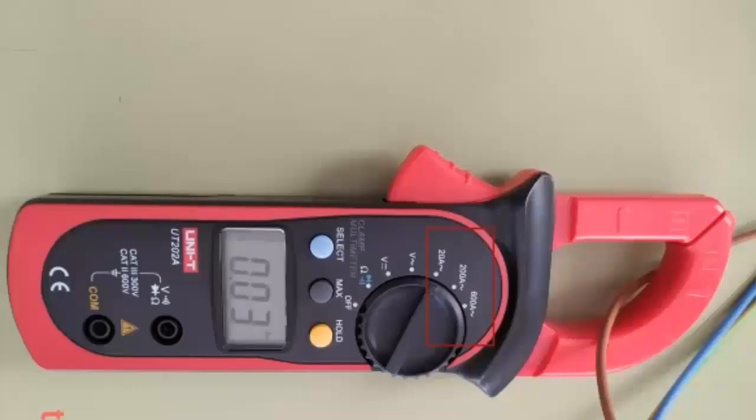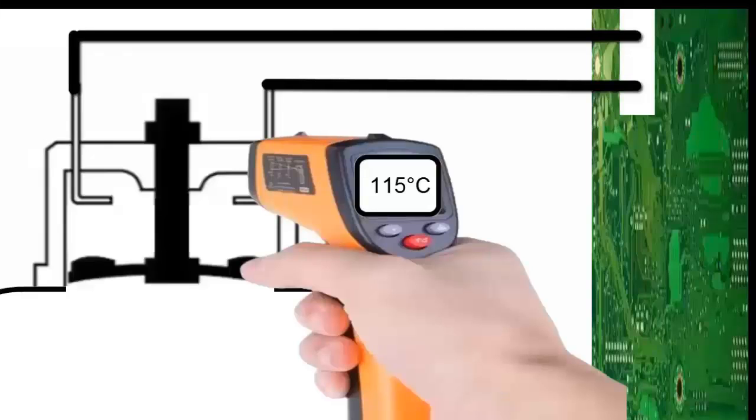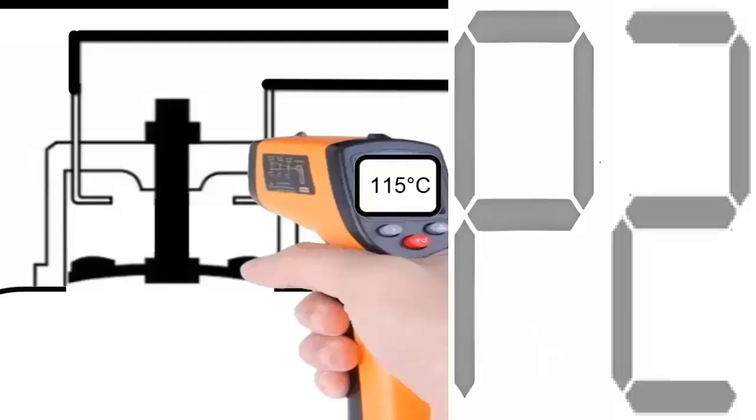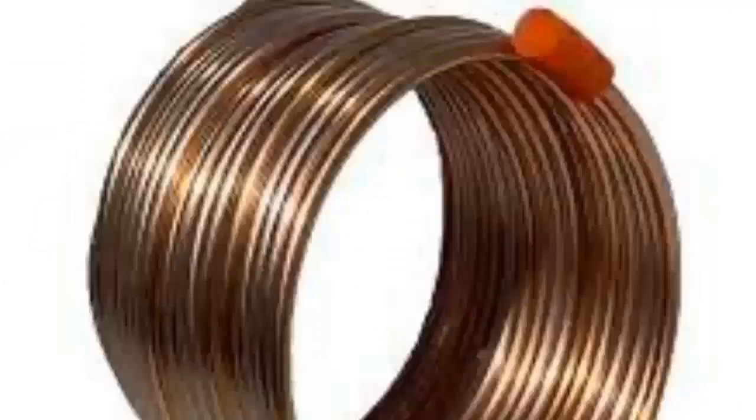It is important to check the power supply voltage from the external electrical network and measure the equipment's current consumption to identify any anomalies. Inspecting the capillary tube or expansion valve, as well as checking the refrigerant gas level, are also important steps in the diagnostic process.